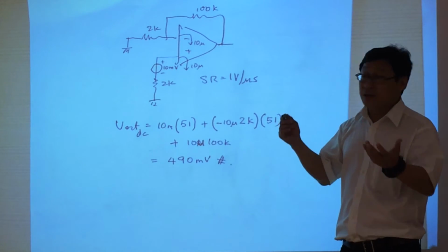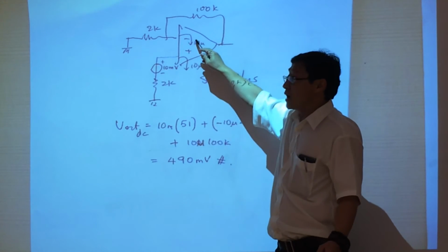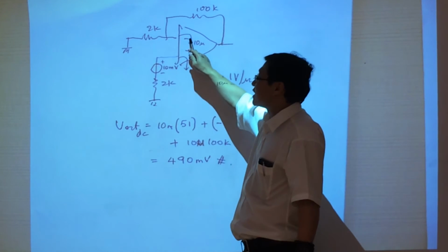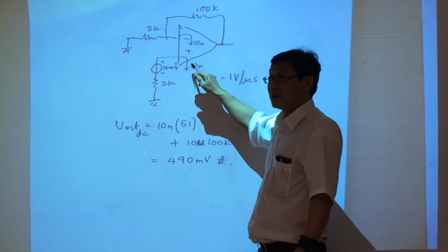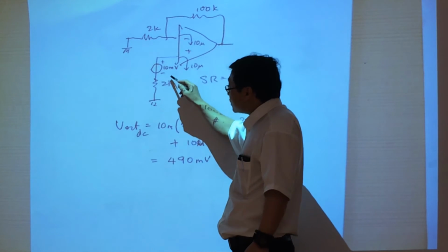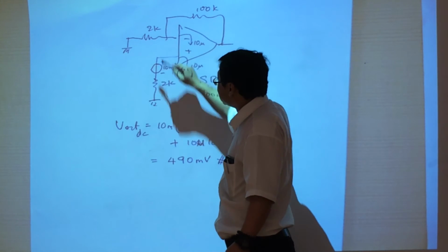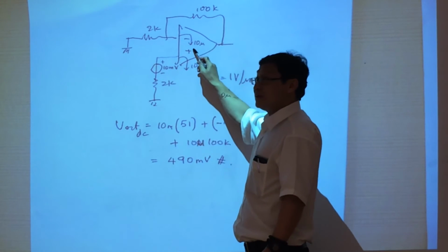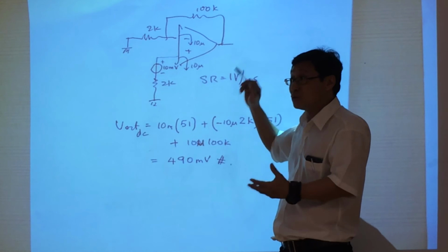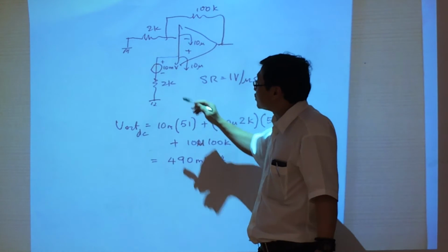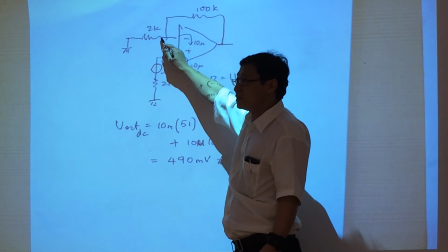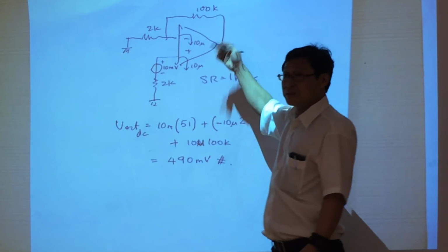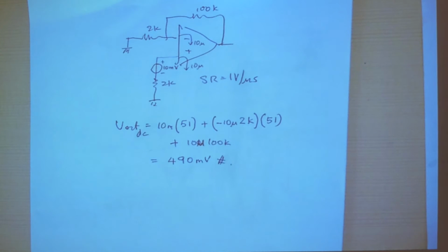Now obviously in production, I plus and I minus will never be equal. There's no chance of having precisely the same current. Therefore, there's no need to put the precise resistance of 2K and 100K in parallel, because we will never have the same current after all. So there's no way you can cancel. You might as well put a resistor that is close and help to bring the voltage down. All right? So basically, that's what it is.